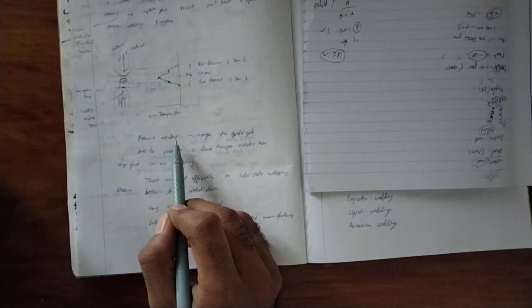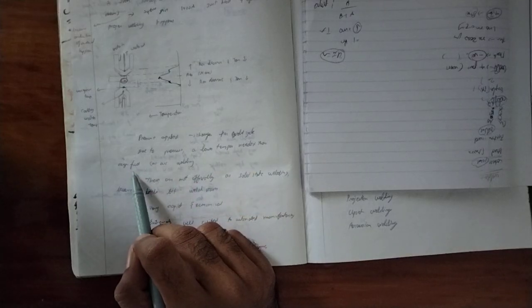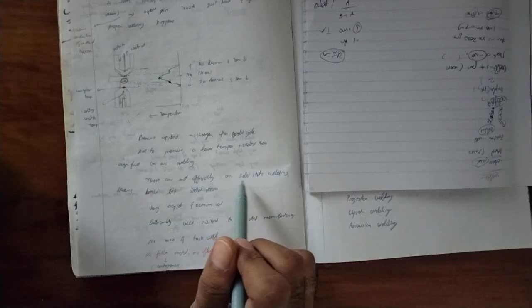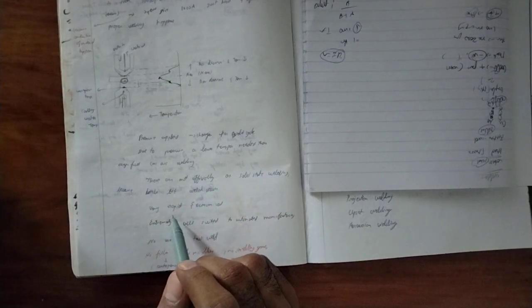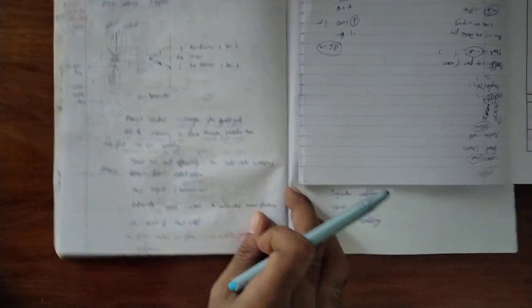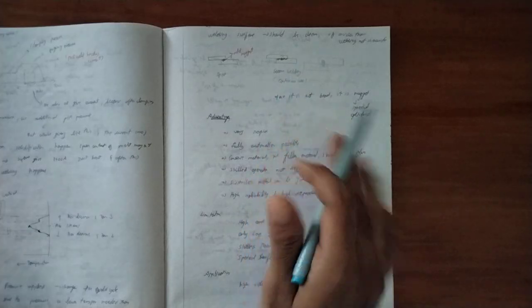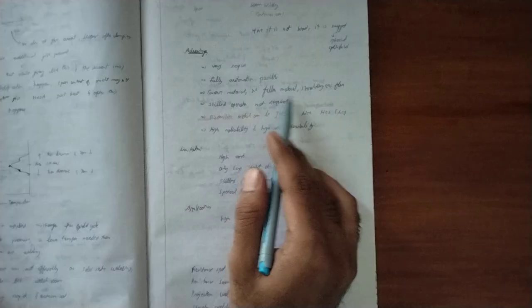Next, you can see the pressure applied changes over the weld cycle. Due to the pressure, a lower temperature is needed than in oxy-fuel and arc welding. They are not officially solid state welding, but a little bit of welding occurs. It is very rapid and economical, and extremely well suited for automated manufacturing. No tack weld, no filler metals, no flux, and no shielding are used. A continuous welded attachment is seam welding. Very rapid, fully automatic, and it conserves materials.